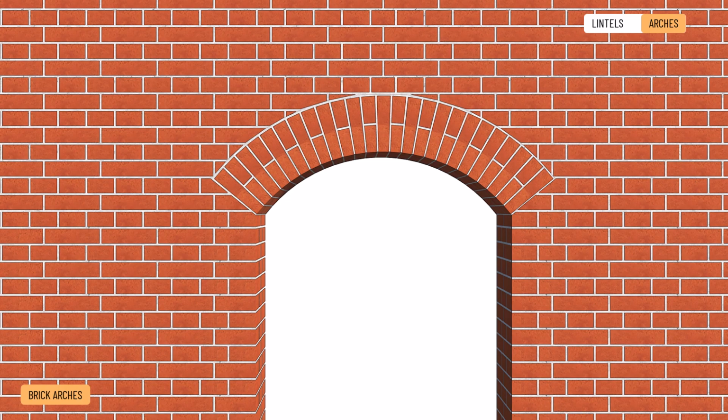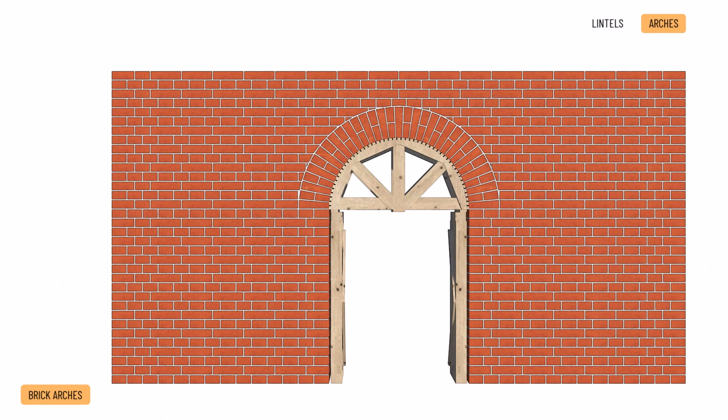In this case, joints with almost parallel sides are created between the wedge-shaped bricks. Arch masonry is only possible using templates. The bricks should be laid symmetrically from both sides of the impost until the two sides meet. The ribs should not be removed until the mortar has set.